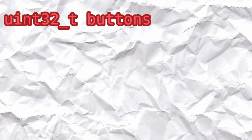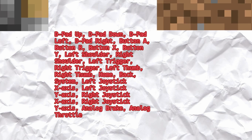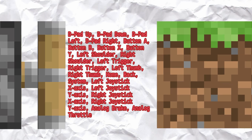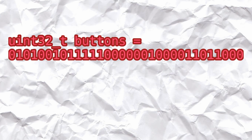Now, a uint32_t is just a number made up of 32 individual bits, and Bluepad32 uses each one of these bits to represent a different button. So instead of storing button A is pressed as its own separate variable, every single button, A, B, X, Y, shoulders, thumbstick clicks, all of it gets packed into that one number, each one corresponds to its own bit. This type of data packing is known as a bit mask.